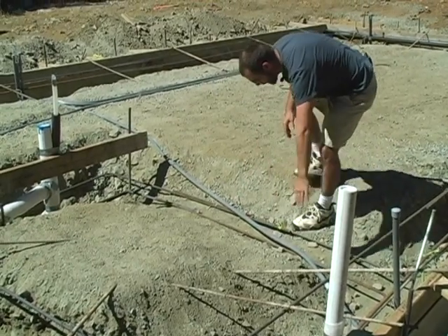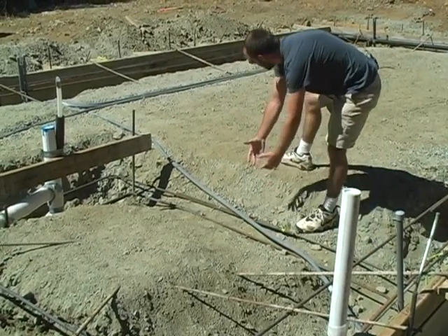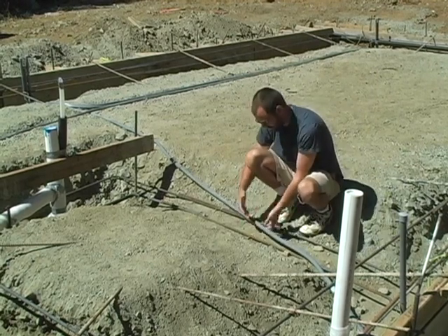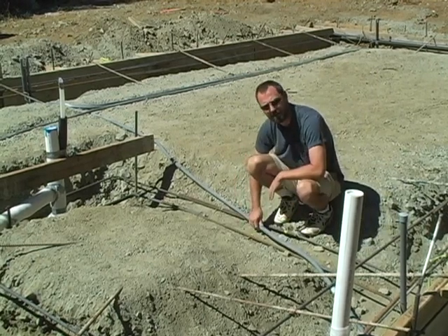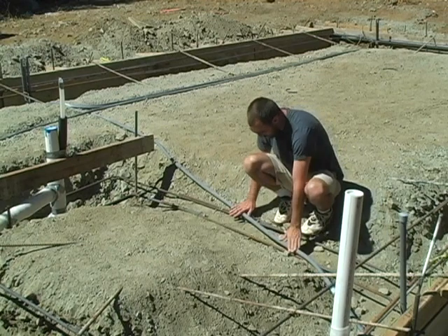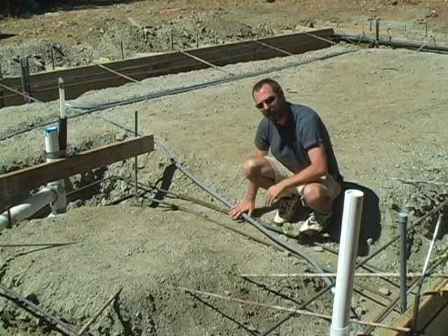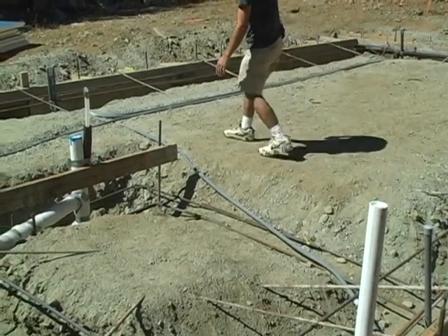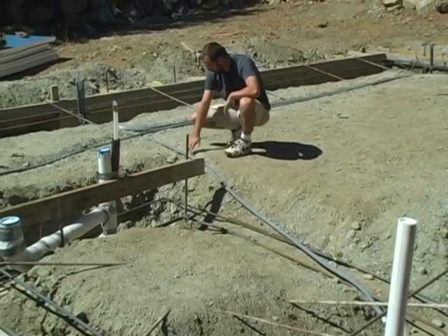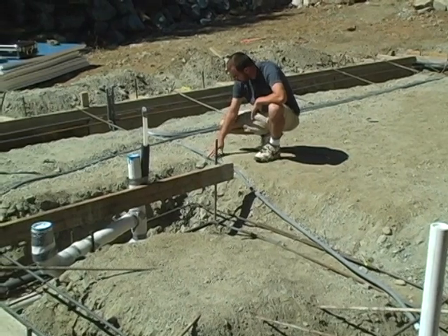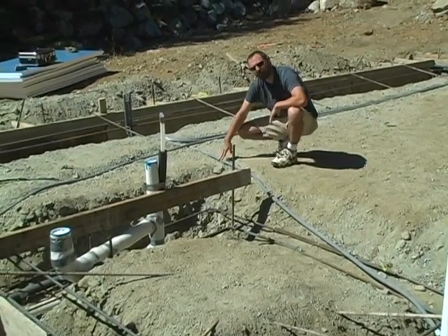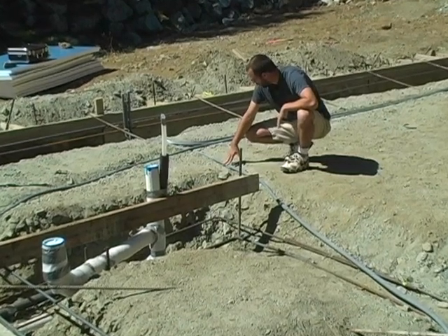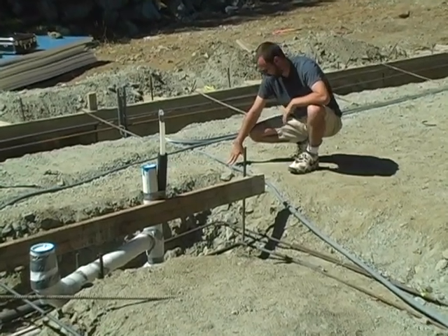And then run this again, keeping it towards the bottom. We don't want to have the pipe up in the air in here without support underneath it, because then when we pour the concrete it'll have a tendency to just snap this under the weight of the concrete. So we got it down where it's supported underneath. Run it along here, again keeping it close to the wall, and we get up into the bottom of the slab area. We've just dug out enough to basically keep the top of the pipe flush with the bed that's going to be our base for the insulation and for the base of the concrete.